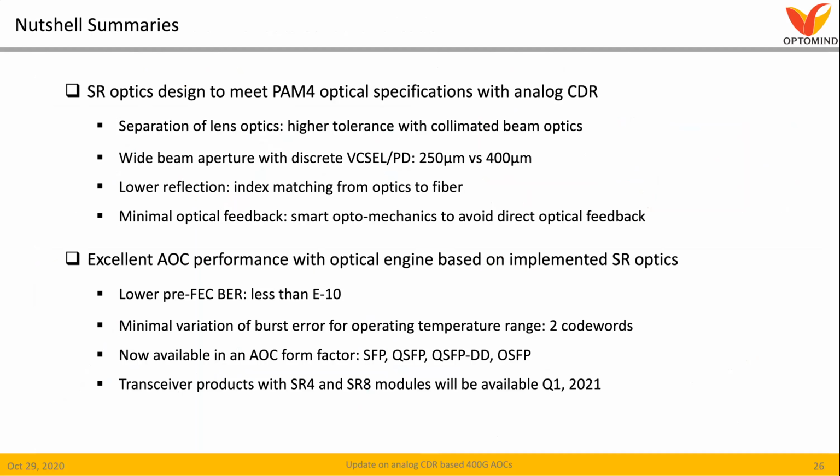In a nutshell, I would like to emphasize the following. We designed and implemented SR optics to meet PAM4 optical specifications using analog CDR. The following are the key features of our optics design. Our new optical engine has demonstrated excellent AOC performance in PAM4 56 Gbps as a result.